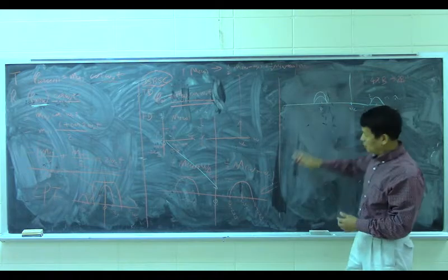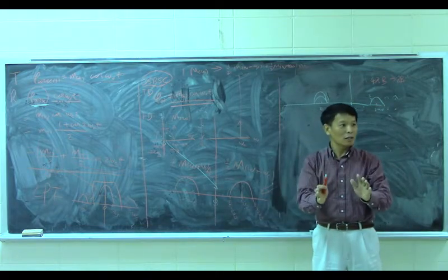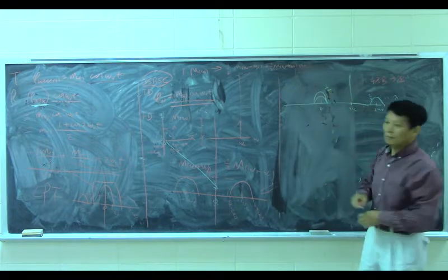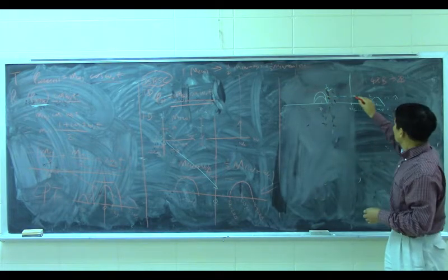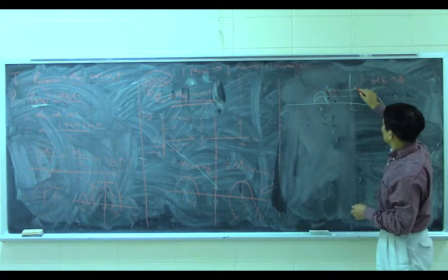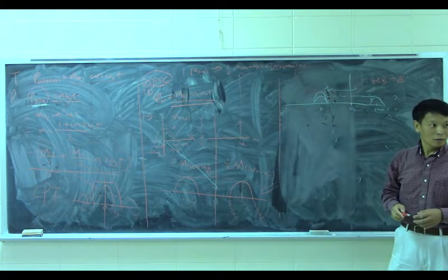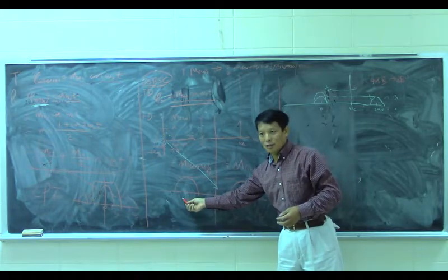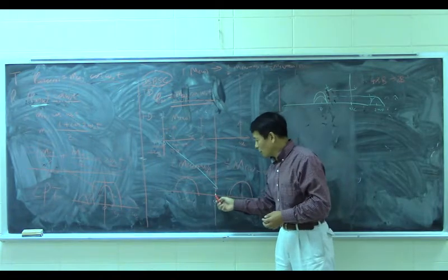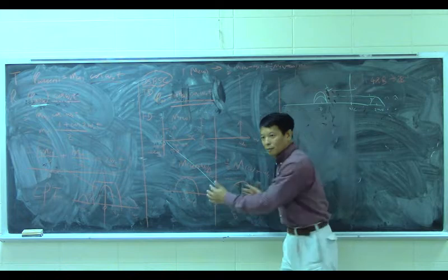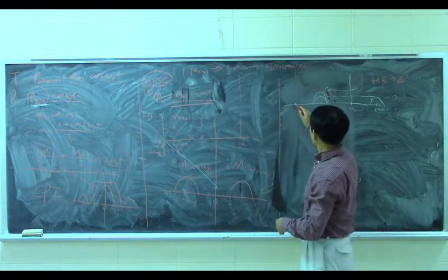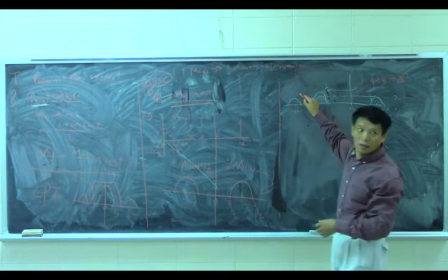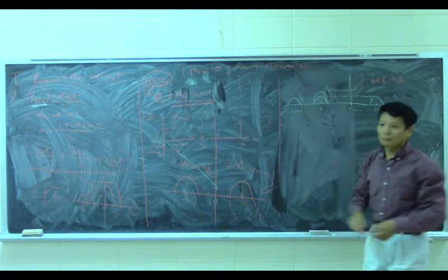So quarter plus quarter, because these two are exactly the same, equals half. So this here is a quarter, this one here is a half. Are you done? Not yet, we still have this one. These two are a team. You only shifted this one to here; this one also needs to go to the left. So we have this one at negative 2 omega c, like this one. And this amplitude equals a quarter. Perfect.